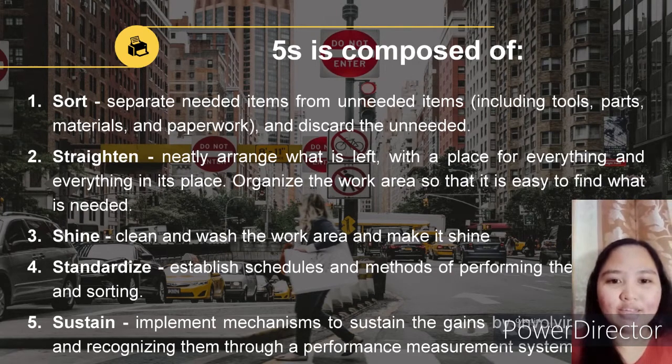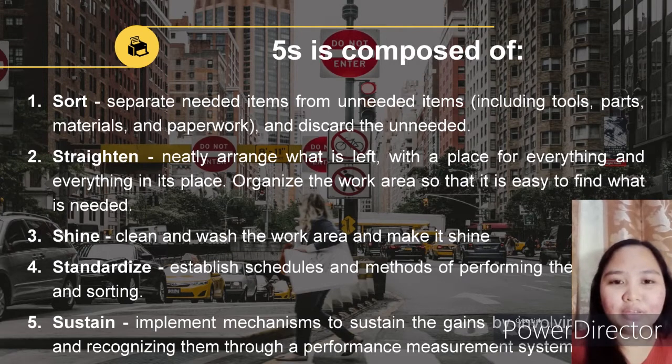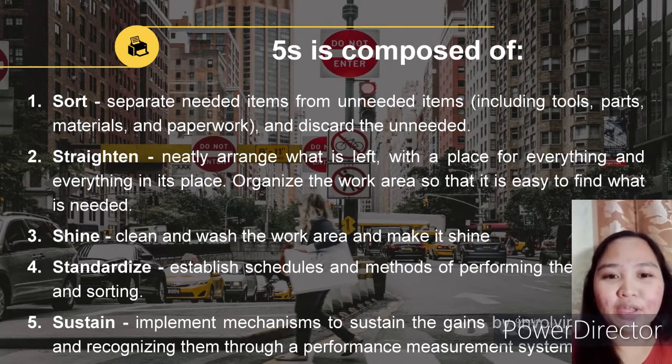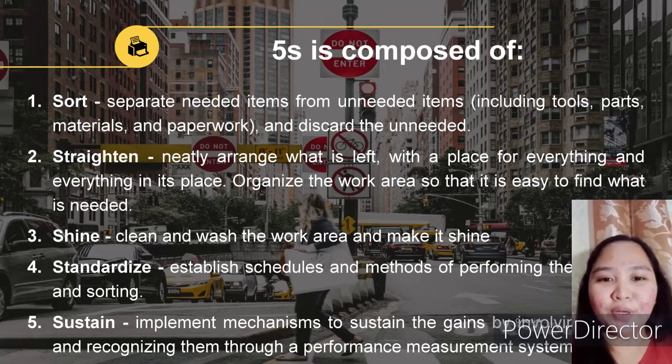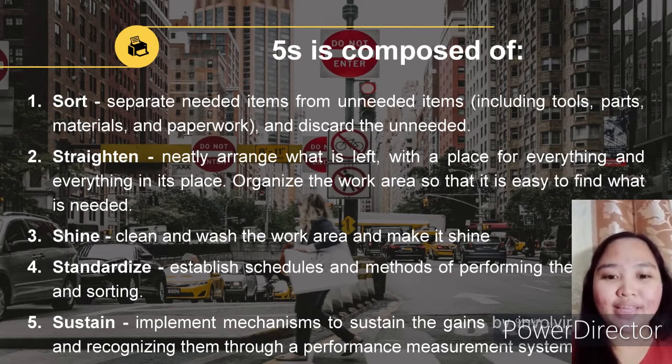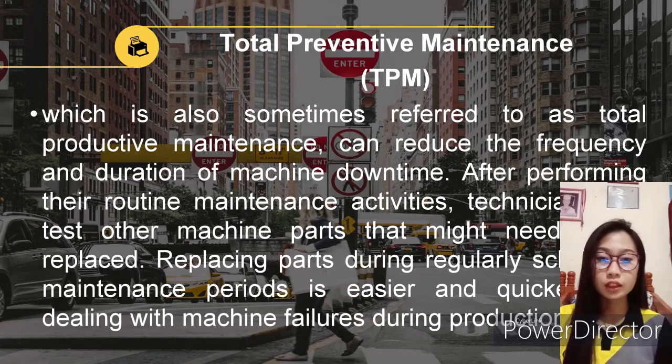The next S stands for standardize. Establish schedules and methods of performing the cleaning and sorting. The last S is sustain. The idea here is continuing commitment. It's important to follow through on the decisions that you've made and continually return to the earlier steps of 5S in an ongoing cycle. Total Productive Maintenance, or TPM.